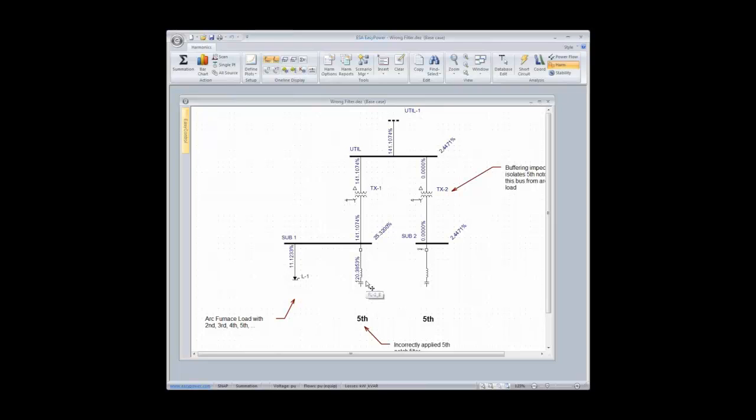Bringing the point home, you need to begin your notch filter application at the point where your first harmonics are appearing. I've actually applied 11th harmonic filters on a system with an active front end, and in that case, they were producing no harmonics, even upwards to around the 17th harmonic, when it was actually some form of switching noise. So let's make sure that when we design notch filters, we properly specify.